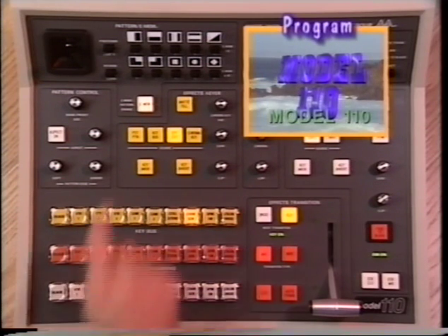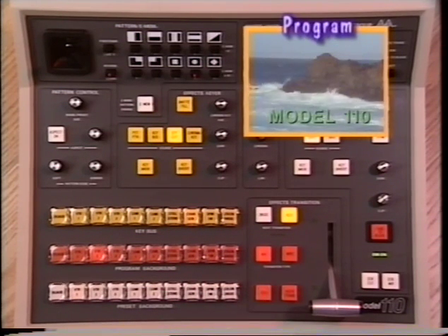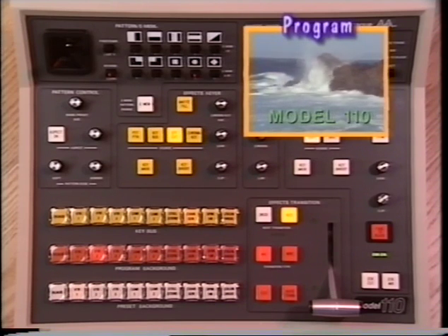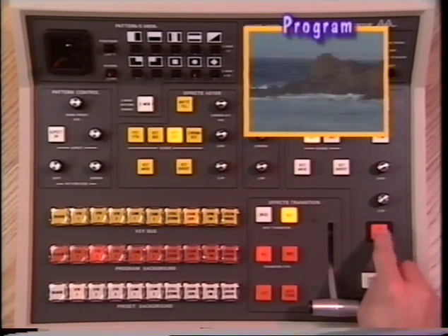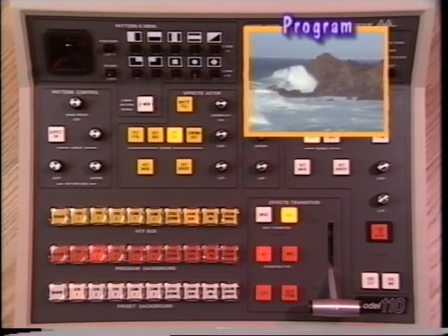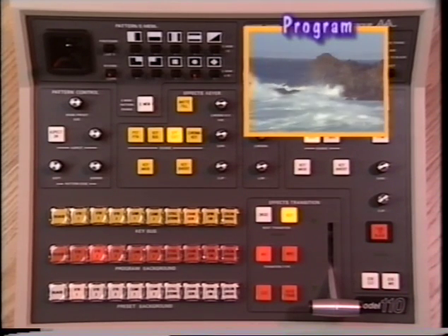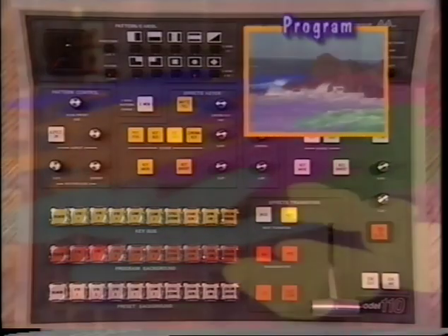Check to see that the eMem push button is off, that the key on lamp in the effects transition group is off, that the downstream on lamp in the downstream keyer group is off, and that the fade to black push button is off. With the switcher properly set up, we're now ready to proceed with the actual operating procedures of the Model 110.